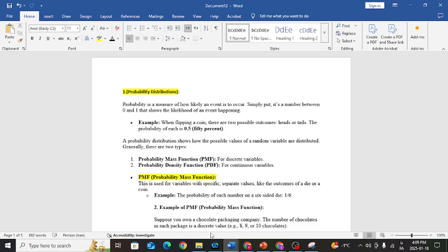Actually, the normal distribution, or we can say the bell curve that all of us, I think, saw this kind of curve, is another cornerstone of quality management. This statistical tool helps us evaluate how consistent a process is and whether its output falls within the desired range. Many real-world variables like the weight of a product, the time required for service delivery, or the diameter of a manufactured component follow a normal distribution.